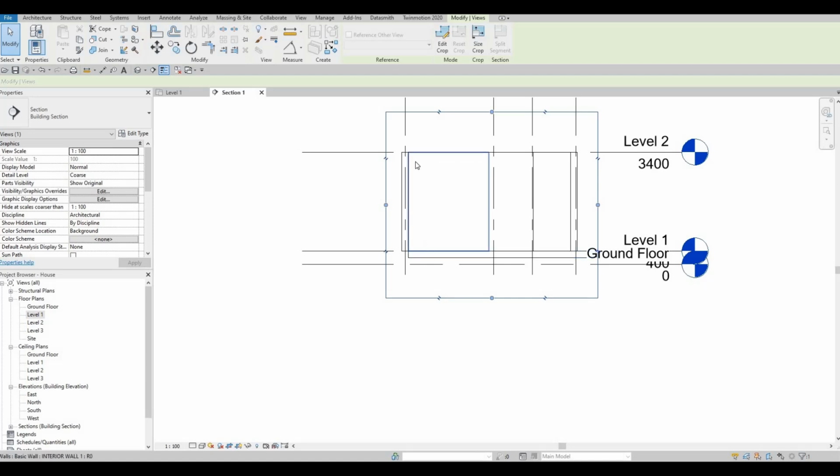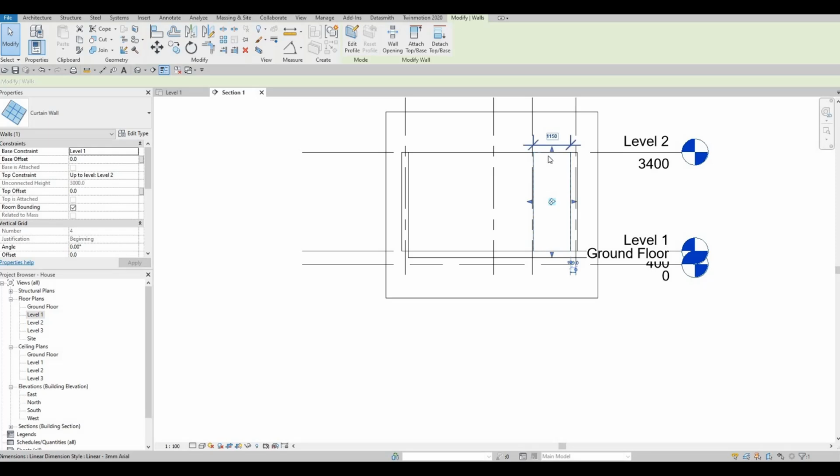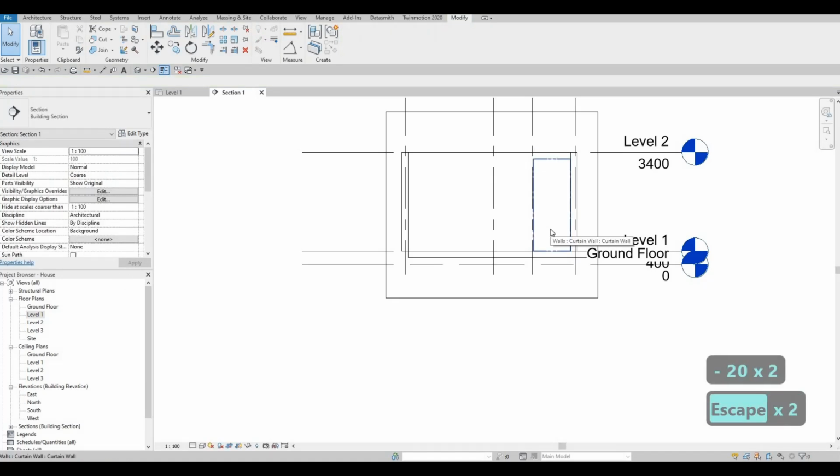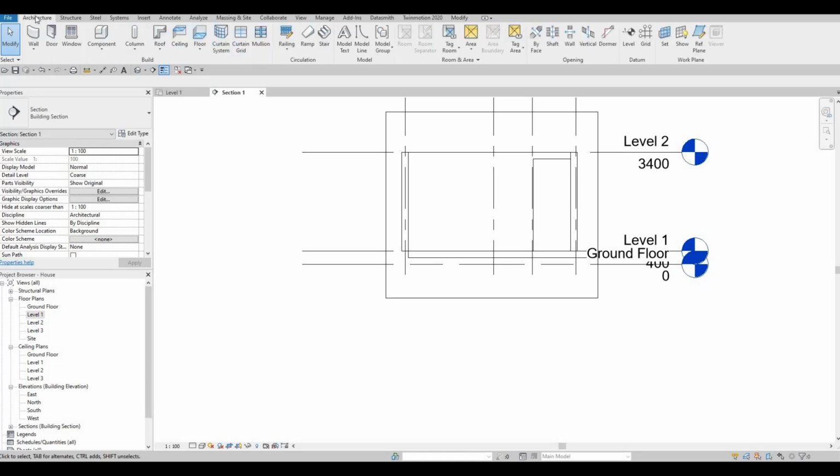Because we're going to add a floor as well right here, we're gonna maximize the height to 2800. So from floor to above, this will be 2800, because we're gonna minus the floor that we're gonna add onto our second floor on our level 2. So here we need to drop this down. Here we can select this and minus 200. So that's the floor to ceiling for that part right there.